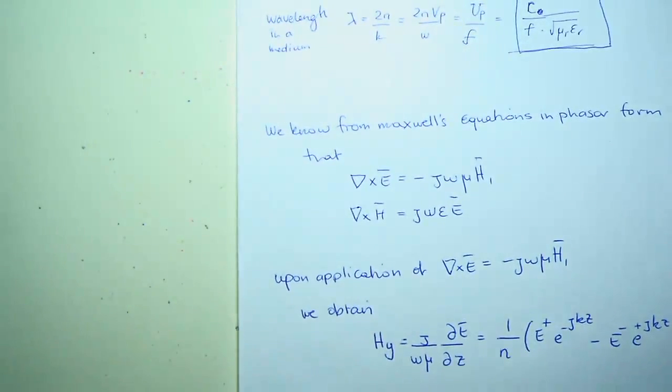So if you had an exam question or you were designing, and someone gave you the characteristics of an antenna in its far field, and I have to emphasize in its far field, this relationship doesn't hold in the near field, and we'll go through this in the next few lectures, you can say to me, Stan, if I know the electric field in the far field, I can tell you what the magnetic field is. So that's what I'm deriving here.